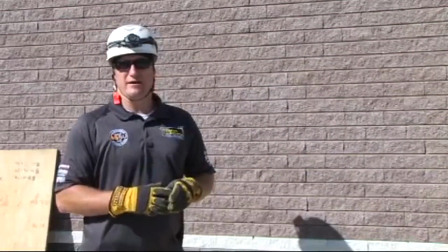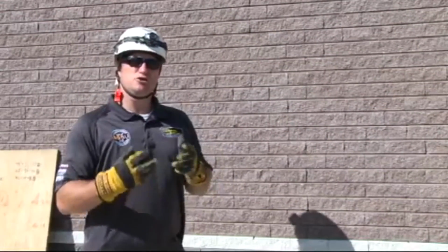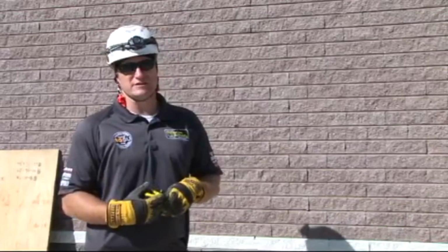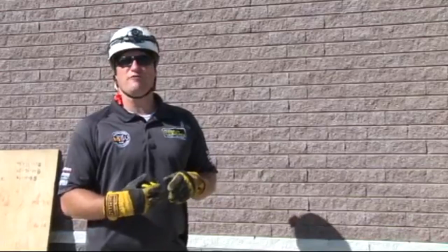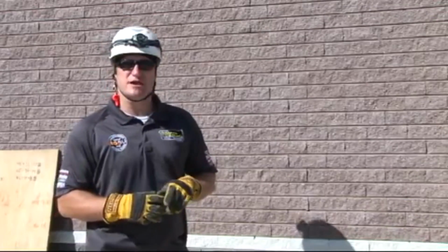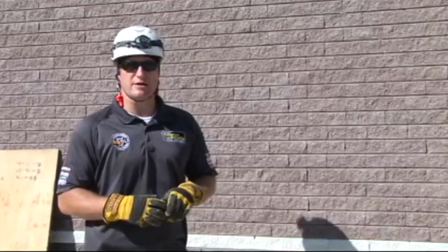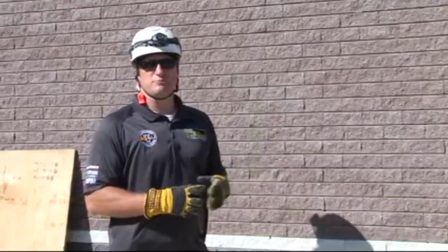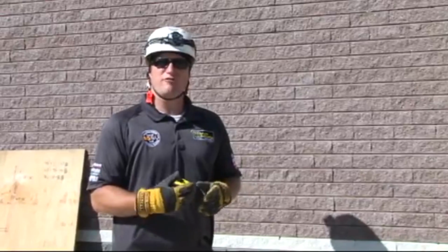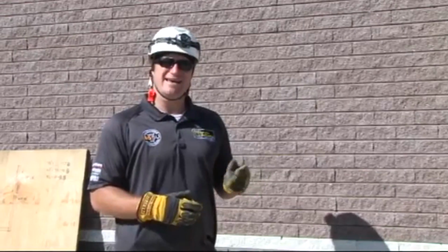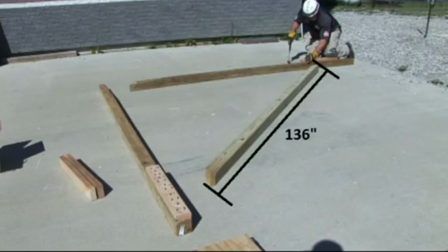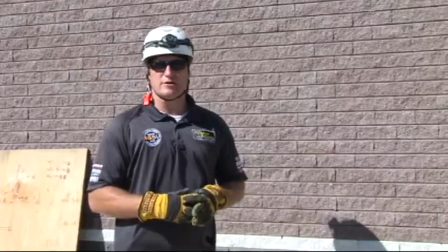Once you have those calculations established, you can use 2 coefficients that are in the FOG manual. One of them is 14 and one of them is 17. The 17 coefficient applies to 45-degree rakers and the 14 applies to 60-degree rakers. So to use that in a calculation method, you're going to take your insertion point of 8 feet. For a 45-degree raker, we would multiply that 8 times 17, giving us a total of 136 inches, or 11 foot 3 inches. That is the length of our raker.